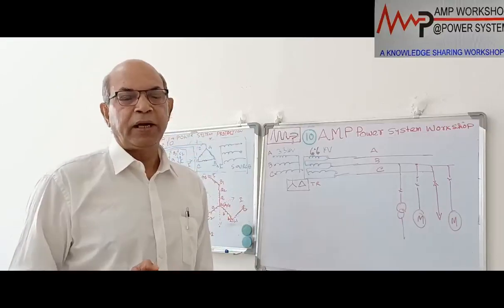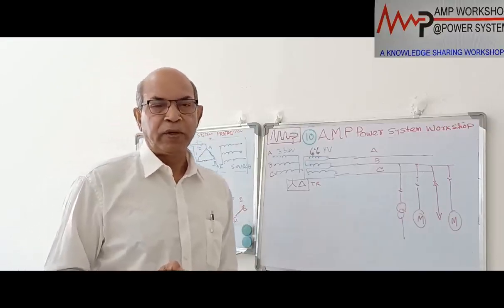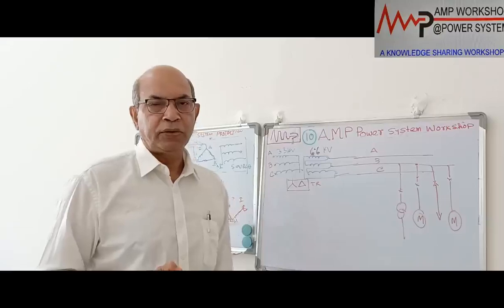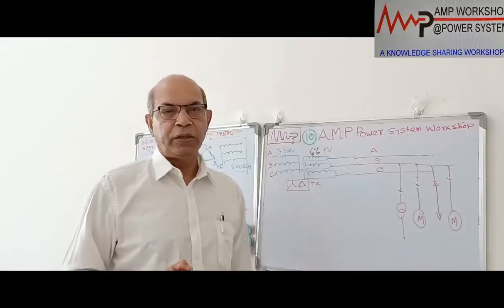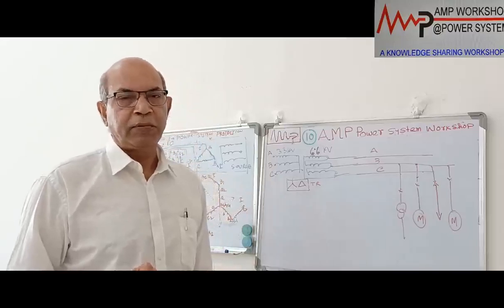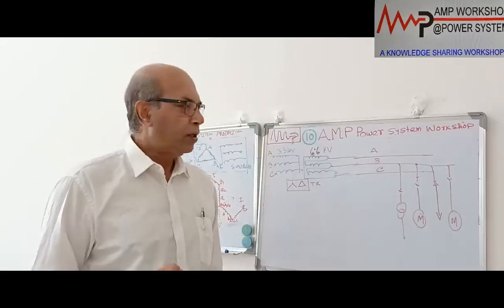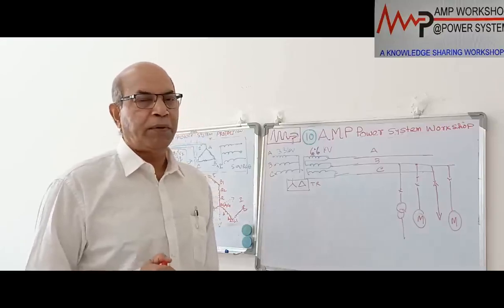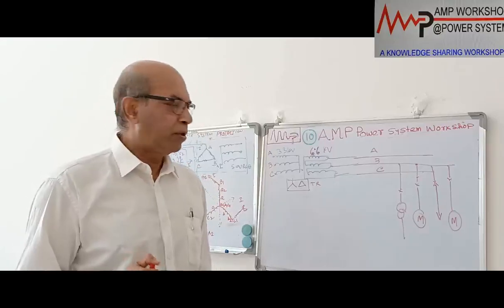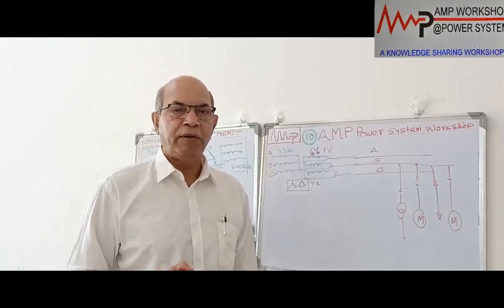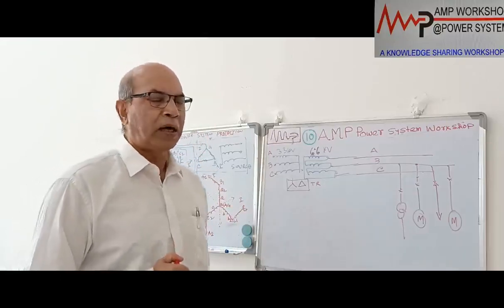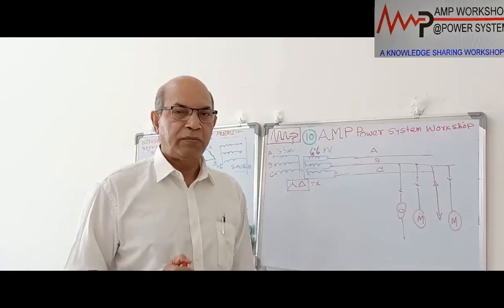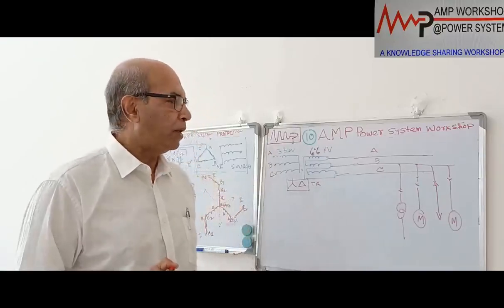They have a delta connected 6.6 kV system, which was designed by the Kuljian Corporation a long time back. It is a 60 megawatt, 5 units power plant. After 30 years, they found that their various 6.6 kV motors were continuously failing due to over voltage. Then they planned to do this earthing arrangement of the delta system, for which I carried out the design part.